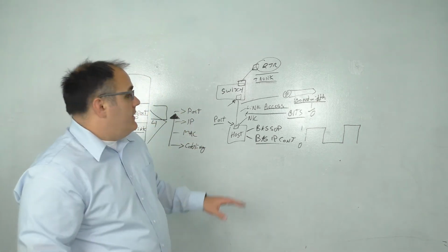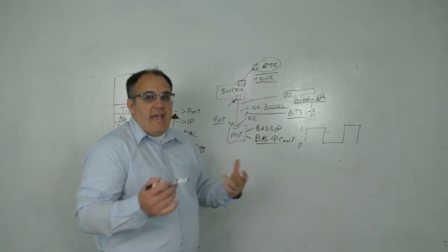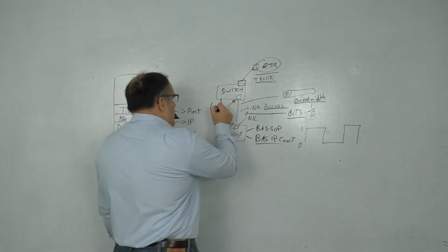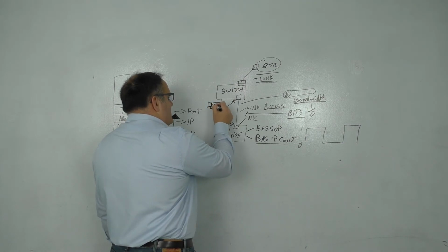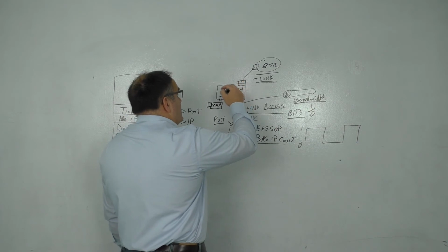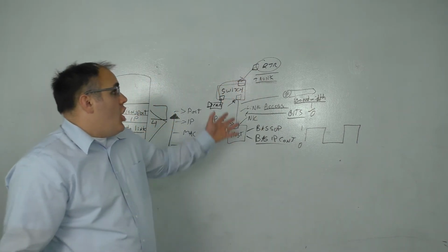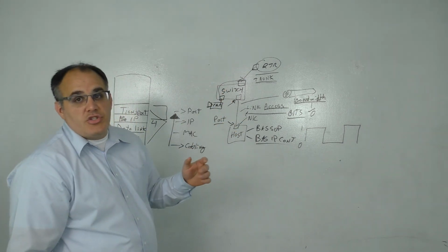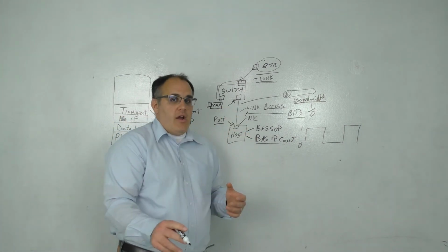That being said, bandwidth at the trunk, this is where occasionally you can have maybe a 4K camera. So a camera here attached. Like I said, I'm not the world's best artist. A camera attached to the switch, and this camera is feeding bits right up here, and the bits going up are more than the pipe can handle, and so your BAS data starts to drop off. That's not as common, but it's something you need to be aware of.